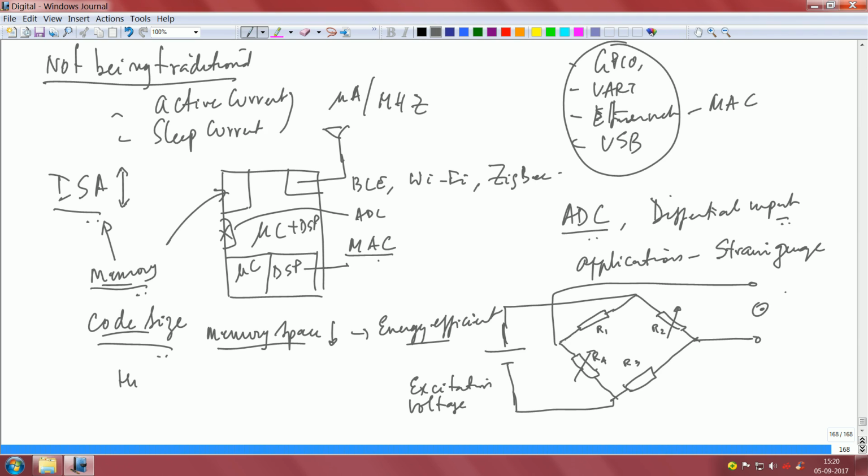Higher end load cells are commonly constructed this way. A load cell basically comprises this strain gauge, and nothing but the load cell is strain gauges in a Wheatstone bridge configuration. Higher end load cells are essentially constructed in this way, with 2 strain gauges connected oppositely. This basically makes the cell twice as sensitive.